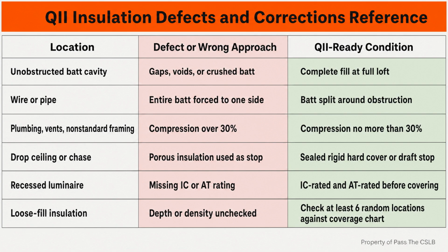Second, field supervision is not energy modeling. A General B contractor should recognize the approved assembly, coordinate the installation, catch visible quality problems, and preserve the documentation path. When a proposed substitution changes the assembly or the compliance analysis, the correct move is to return to the responsible design or energy compliance professional and the authority having jurisdiction.